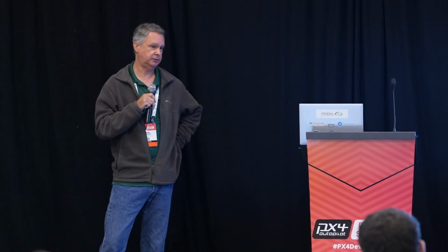Eric? Are there any tools available to profile the DSP to get a little bit more insight into how much resource utilization is happening? Yeah, great question. So, tools to profile DSP resource utilization. There's a number of different things. In the SDK, there's actually a profiling tool that will do kind of thread-level profiling, and we have that enabled within the kernel that's running there. So there is a way to do that. I wouldn't call it straightforward. It's a little bit challenging to get that going.